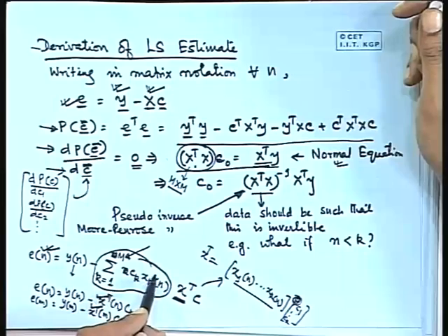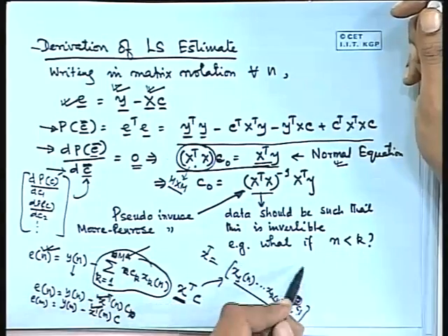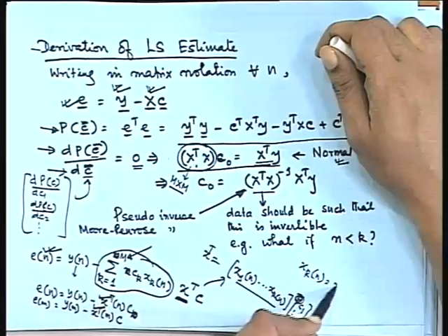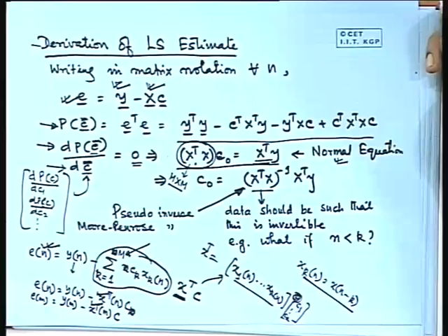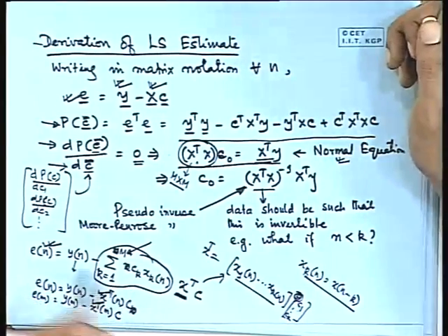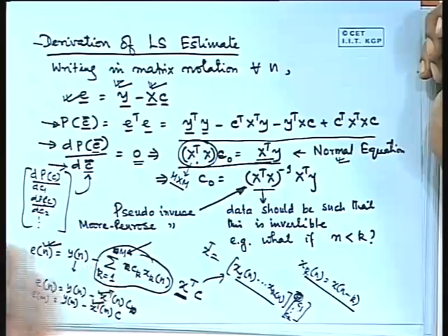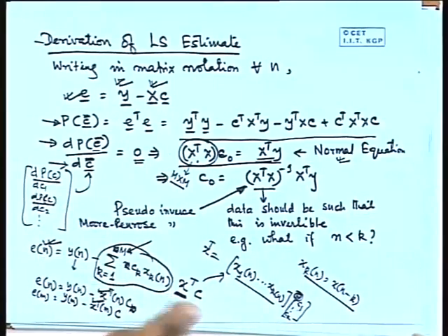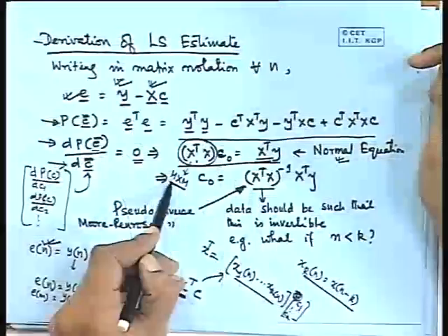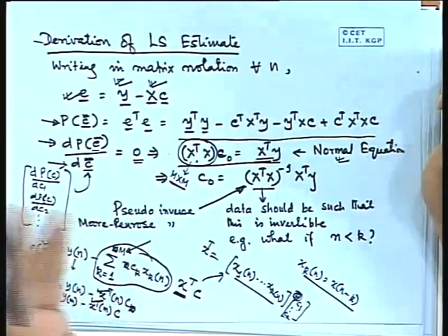See, when you are doing an FIR, why I say FIR, because this is a very general description. You can always write that xk[n] is equal to x[n minus k]. You can always define xk[n] in that way. Then it will become a true FIR filtering. Now I'm saying FIR filter, but it's not. It's actually as if data is coming from capital M different sensors, and we are making them sum. This equation looks like that. So it's an M into M matrix. It is square, but we don't know whether it's invertible.